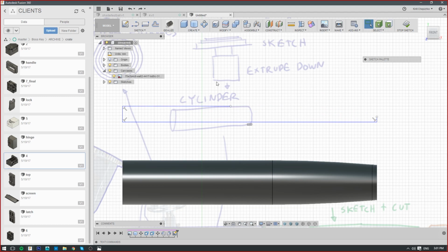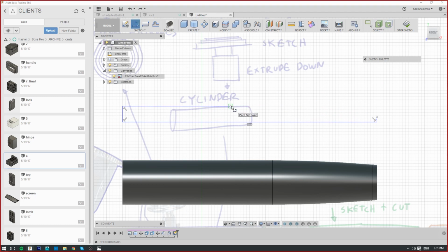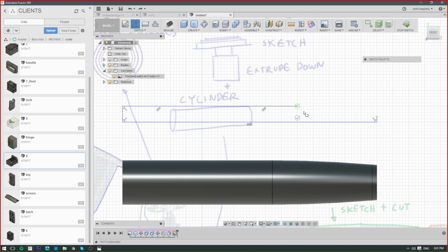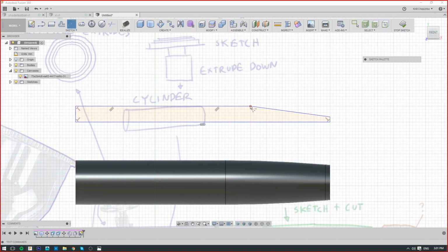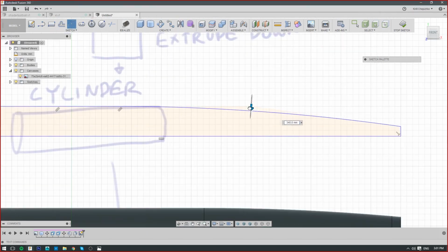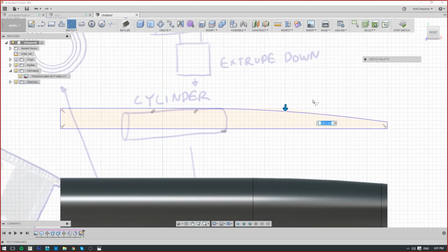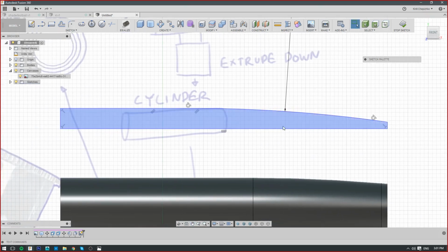But another good way would be to estimate where that curve is going to be turning, have it like that, and then just close this, add a fillet on this edge, and it will tell you where it makes sense to stop, kind of. So definitely several ways. Let's say we're satisfied with that.